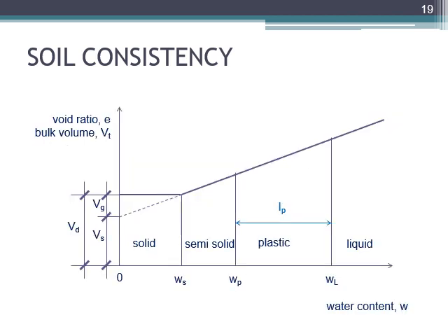Let's see what is happening to a clay sample when it's being dried. This point has the coordinates Wn, e. Wn is the natural water content, and e is the current void ratio. On the vertical axis, we could show here either the void ratio or the bulk volume of the sample, because they are interrelated.